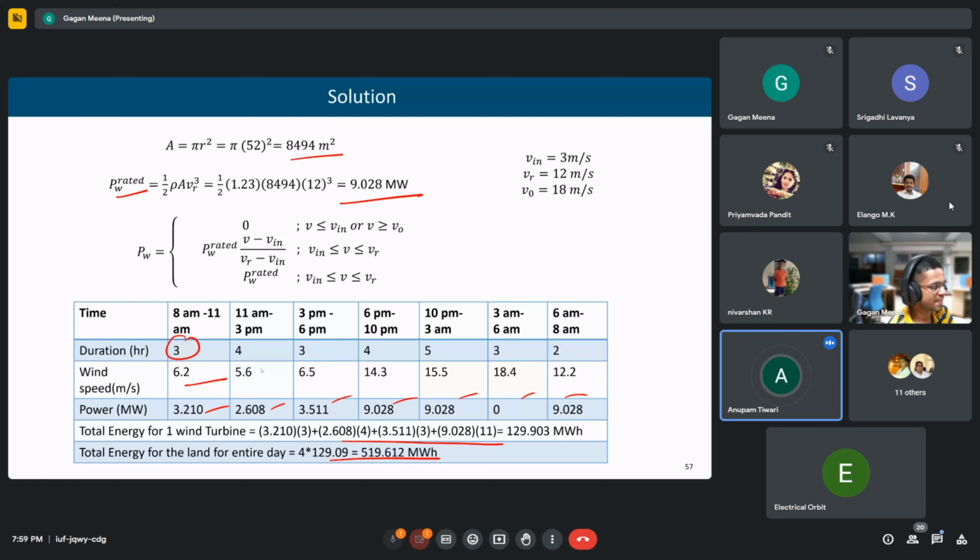But practically, what you said now, that type 3 is there, that the speed is changing, but I don't know. I have never seen that it's constant. Pitch control is used there. So even in that type 3, pitch angle control is used. Yes, they use it. Now all the turbines use the pitch control.